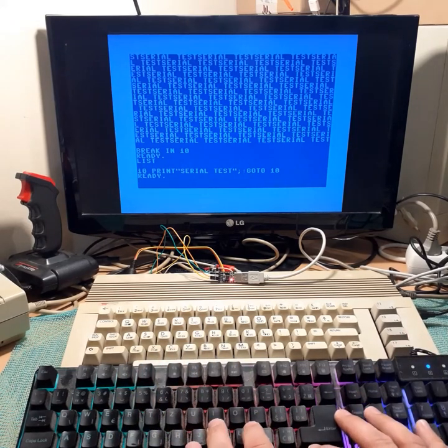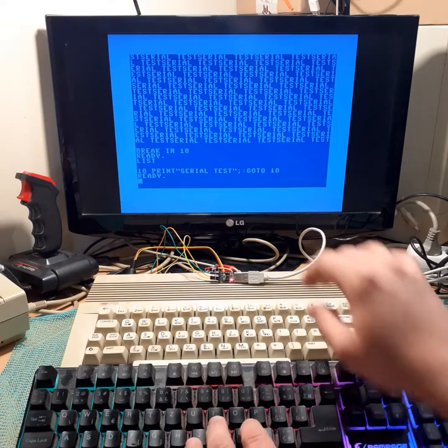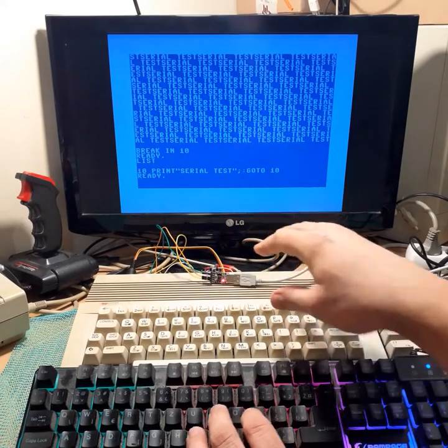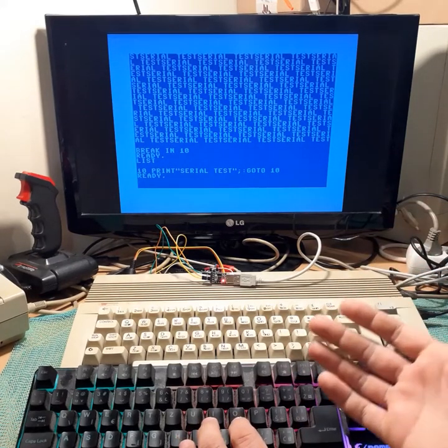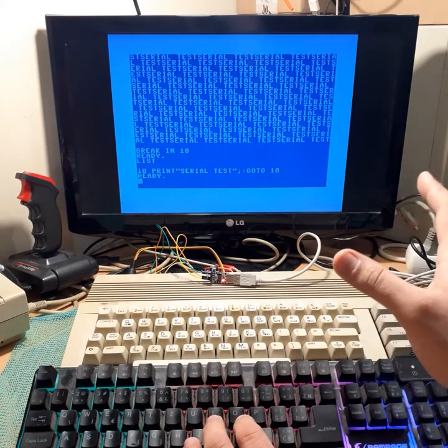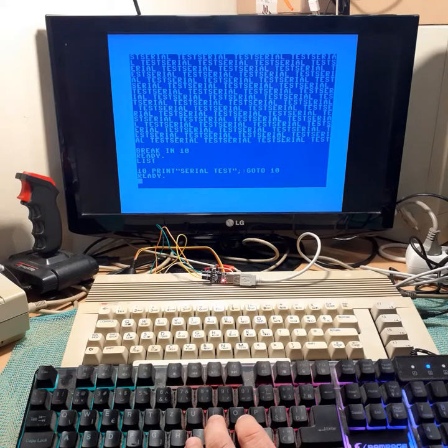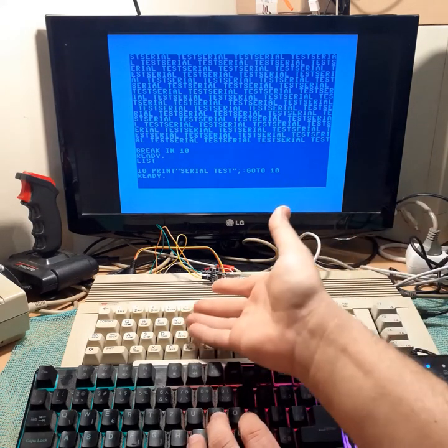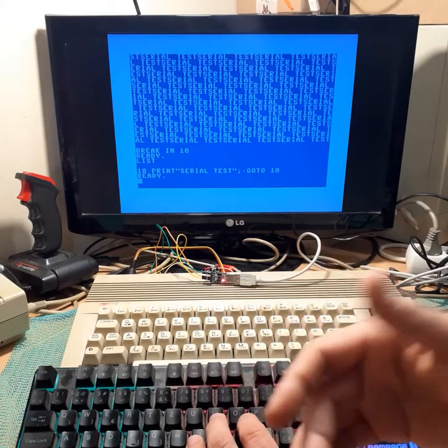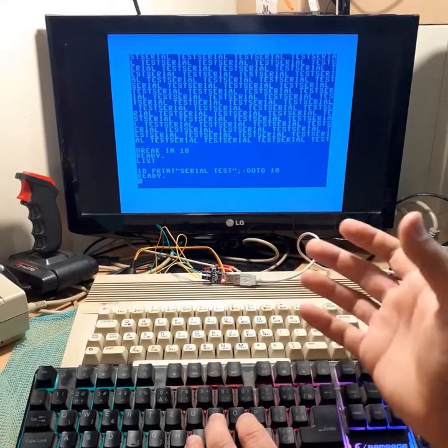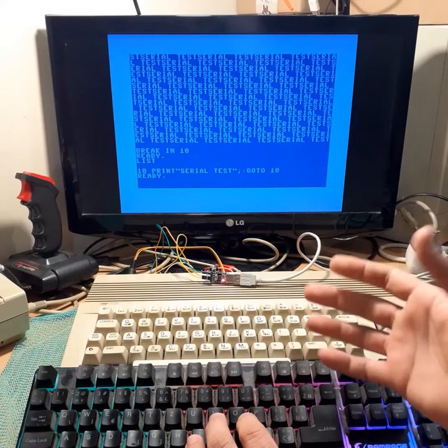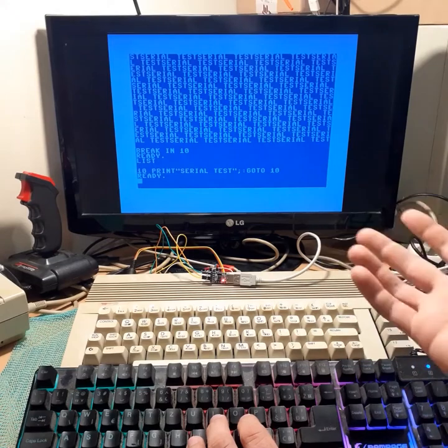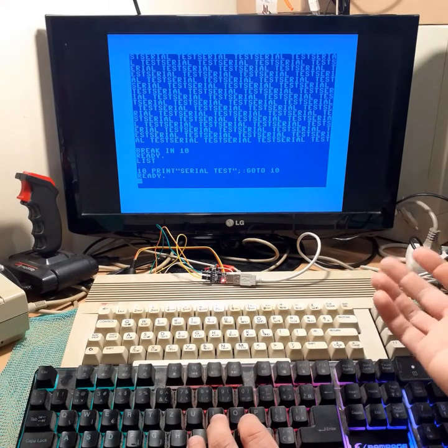It uses raster interrupts to capture any information coming from a serial port, and instead of just outputting directly to the screen, we fill the keyboard buffer of the Commodore 64, and to constantly tell, in case that we have something in the keyboard buffer, we just tell the kernel that there is something there and to process it.